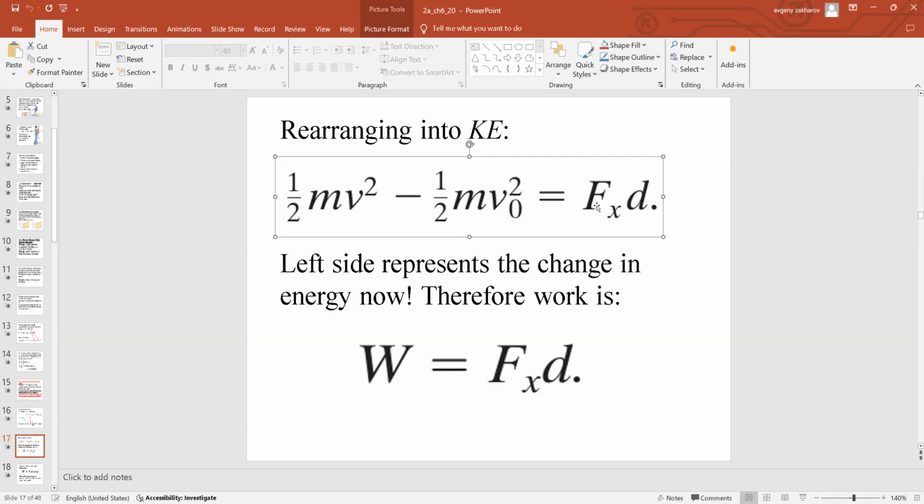So that's why you have only the component that is adjacent to a certain displacement vector, and that's why you have a cosine of angle on the right as well. So work is force dot displacement, or you say force by itself, displacement by itself, and the cosine of the angle between the two vectors. And you can see how work is also a change in kinetic energy. This principle is what we're going to use all the time to solve all sorts of problems.